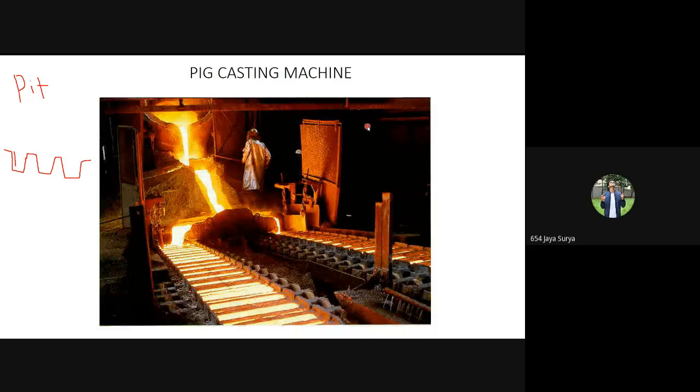Silicon. They add it. They do treatment, ma'am, so those are known as inoculants. You remember inoculants? So when you add inoculants, you get gray cast iron or spheroidal cast iron after treatment. Why? Because the carbon can be in the form of spheroids, that is spheroidal cast iron, or ductile cast iron, or simply gray cast iron, where it is in the form of graphite flakes.